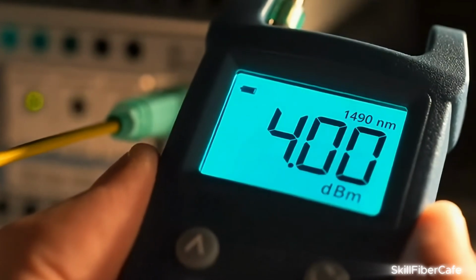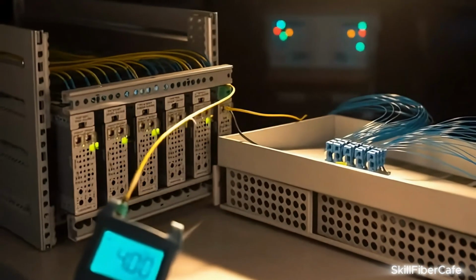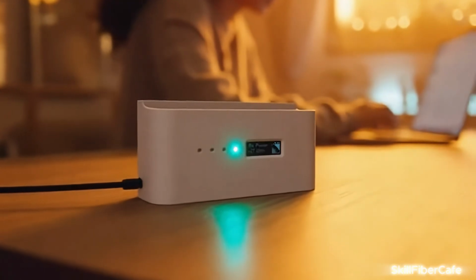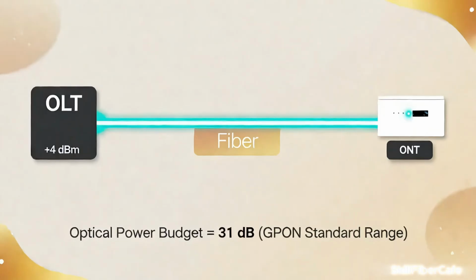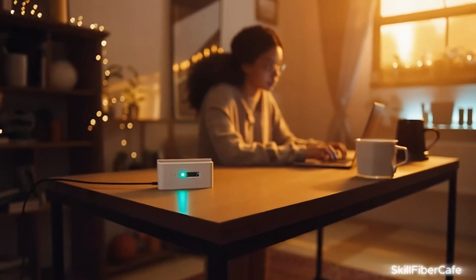The OLT is the source of power. Typical GPON transmitters generate around +4 dBm optical power at 1,490 nanometers. This becomes the starting point of all calculations. The ONT at the subscriber end can detect as low as -27 dBm. The difference between output and sensitivity sets the total available budget, roughly 31 decibels, for GPON.